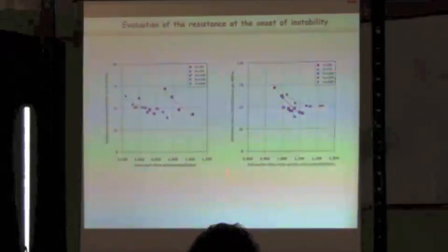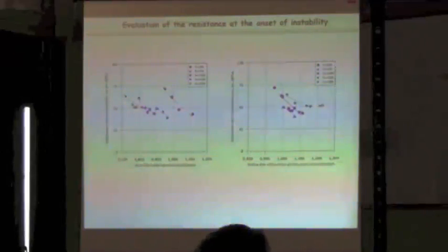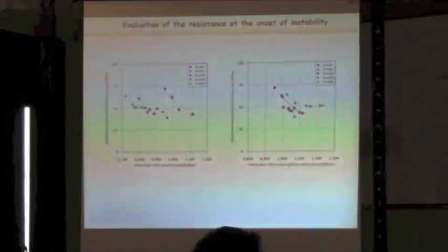The other point here is that when we are dealing with diffusion, the more appropriate parameter to use is the intergrain void ratio, because when the diffusion happens, we have the washout of the fine particles, but the sand skeleton remains constant. Then we have to use the intergrain void ratio.